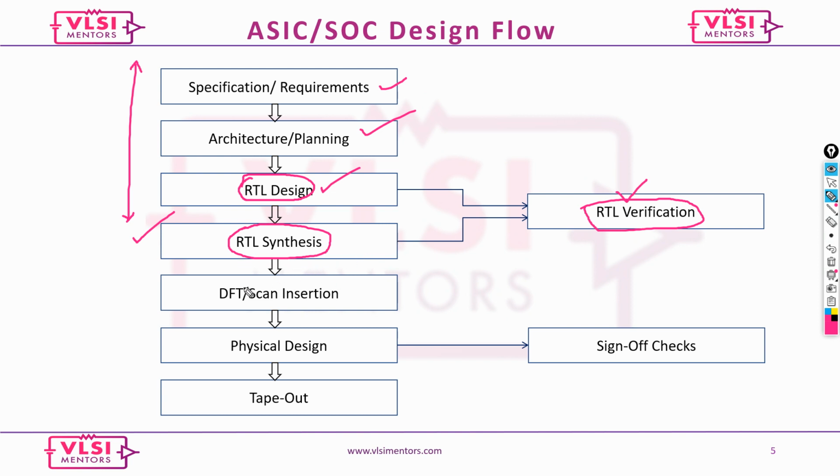Okay, so once you're done with that, any chip that you've designed needs to be tested. So the DFT will come into the picture. The DFT team would come and come up with certain testing plans. This is the architecture that we want to insert, so that once you design the chip and it gets fabricated, this is how we are planning to test it. So they insert the testing logic.